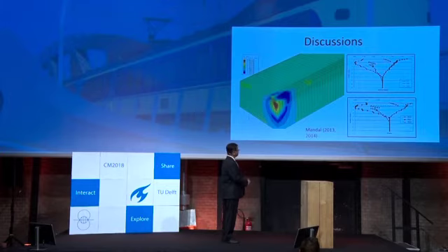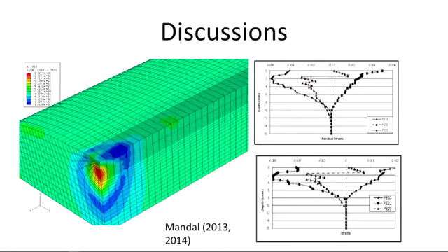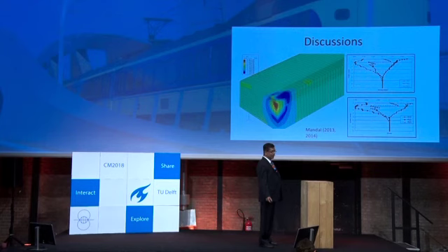We are talking about this, but what is happening close to this surface? You can see this is the result. This is the elastic behavior, and you can see that somewhere between 8 millimeter and 12 millimeter there is no plastic deformation after that, so it is elastic. Definitely in the joint area it is elastic behavior, so Miner's rule is important.